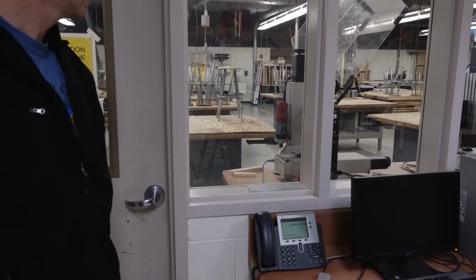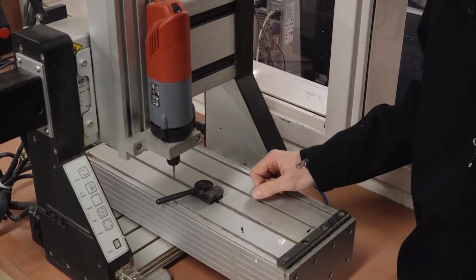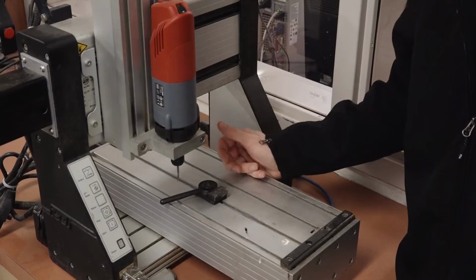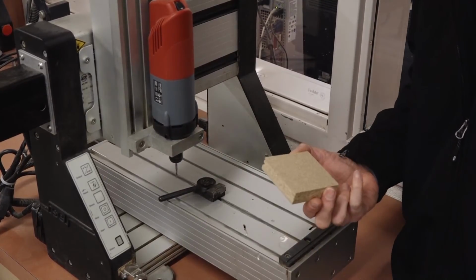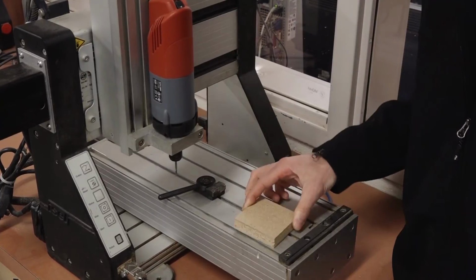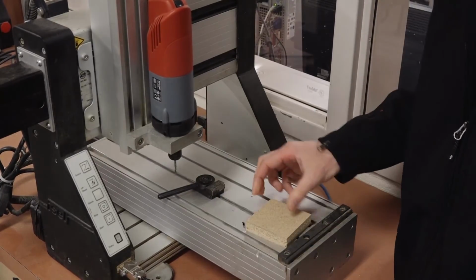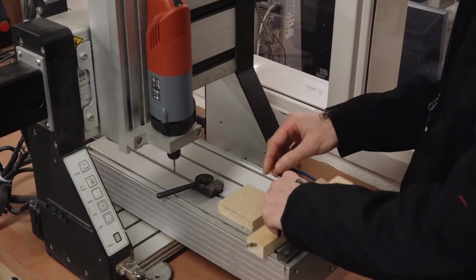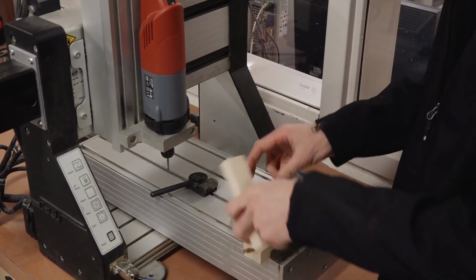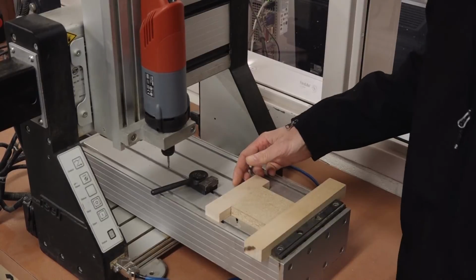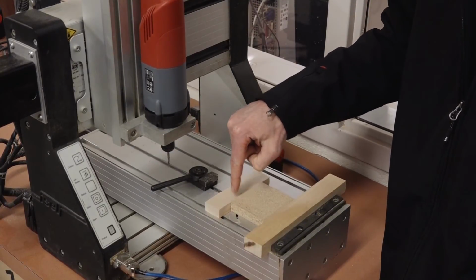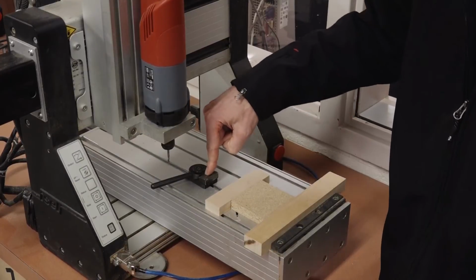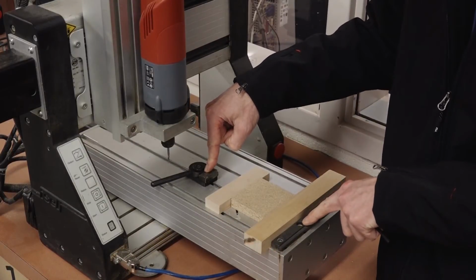The only other thing I'd say is when using one of the Da Vinci CNC mills, one of the first things you have to do is stick whatever the part is into the mill and get it in there so it's secured. And this clamp does that for you. If you're going to mill to the edge of a part, you need to use blocks like these, sacrificial pieces, so that when the mill goes off the edge, it goes into this wood and not either of these metal clamps.